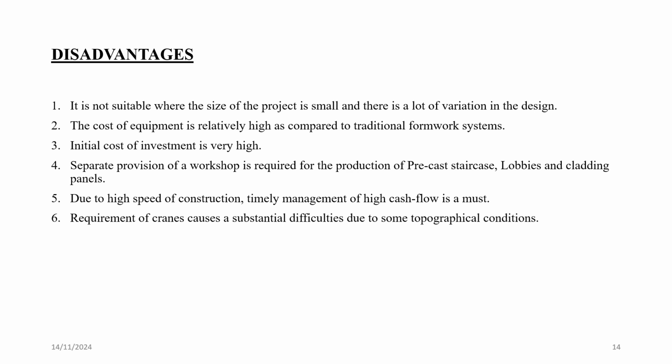Fourth, separate provision of a workshop is required for the production of precast staircase, lobbies, and cladding panels. Fifth, due to high speed of construction, timely management of high cash flow is a must. Sixth, requirement of the cranes causes substantial difficulties due to some topographical conditions.